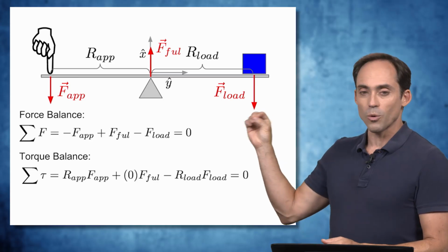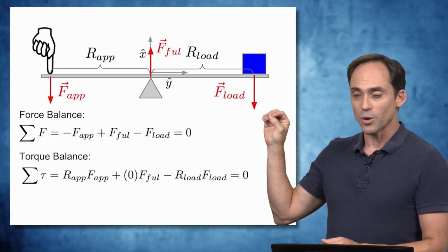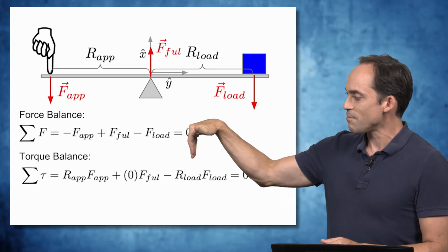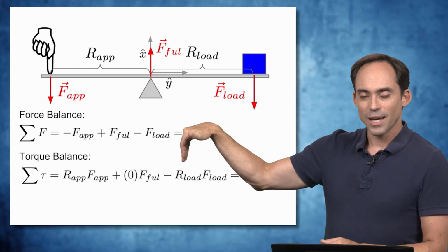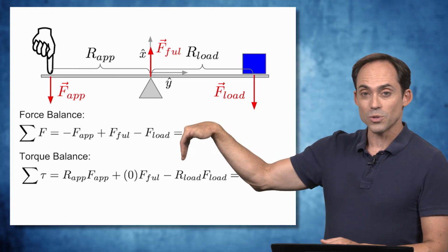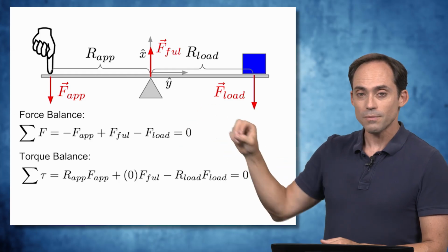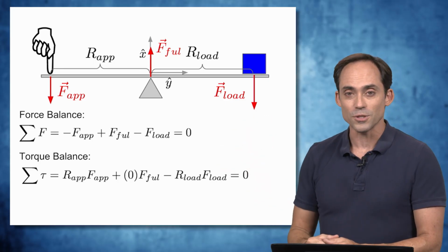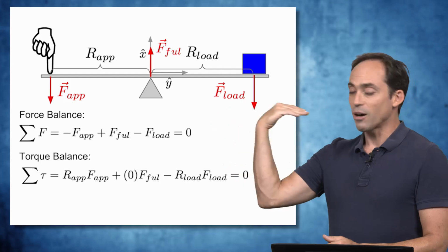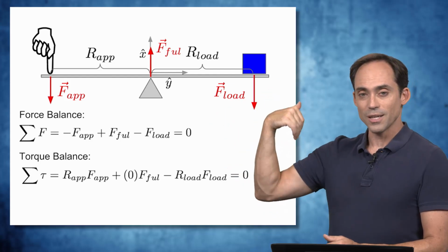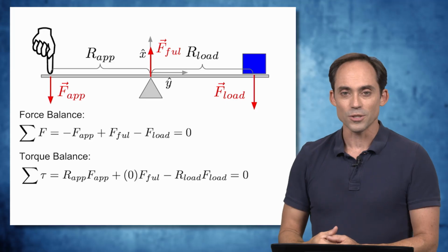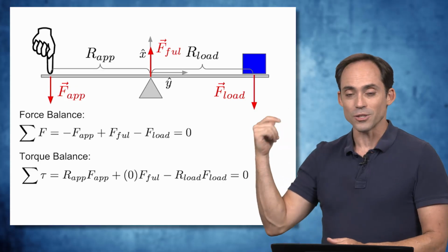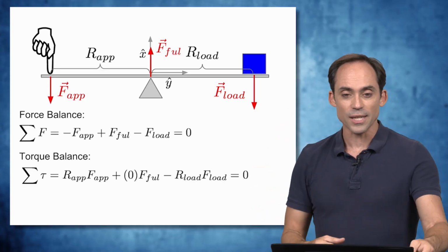So we can go through and calculate these torques. Starting from our coordinate system in the middle, we can calculate the torque for the far end of the lever where the force is applied. So it's R cross F, and that's pointed out of the board. And notice I've not put a direction vector, but I'm just going to choose that to be positive for this problem. The fulcrum contact force is right at the origin, so it's not applying any torque at all. And the load force, R from our origin cross F pointing down, is pointing in the opposite direction as our applied force. So we can write that as a negative torque, keeping in mind implicitly that means it's pointing in the opposite direction as our first torque. We add those together, that's 0.